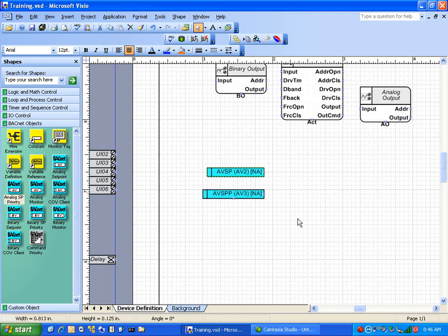If that object is linked to a graphic and you view it, that's when the BACnet object actually polls, and it's the only time it polls. So that's perfect for doing things like space set points and other manually selected set points. That's when the analog set point priority gets used the most. If you know you're going to go directly to a graphic screen, you can change that right-click functionality to say whatever you want. Usually by default we do set because it's the easiest to program. It's quick and easy to edit in the visual tab, and that's the main reason. And it can sit in a poll-on-demand container, and now we've got less traffic, which is nice.